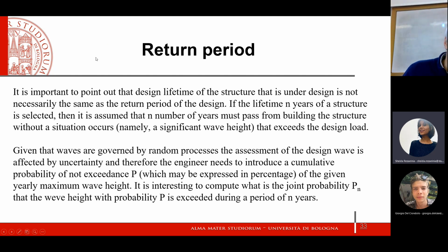So, determination of the return period. We need to understand some more because in some cases we may be asked to give our contribution to that. And the return period, some people basically think that it should be the same as the expected lifetime of the structure. This is not really true, and it's not necessarily the same. It is comparable in general, but not necessarily the same.